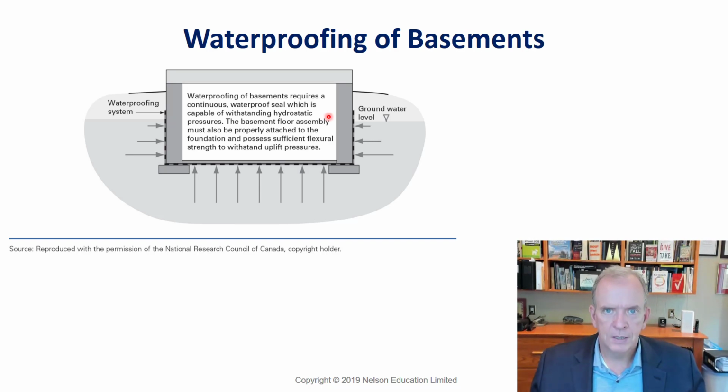So you've got to respect hydrostatic pressure, and you've got to make sure that the amount of time that it takes to put bracing is hardly anything. In an hour, a good carpenter can have the whole thing all braced up, compared to the days and thousands of dollars it takes to fix a foundation that's settled.